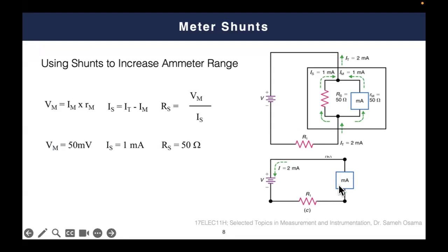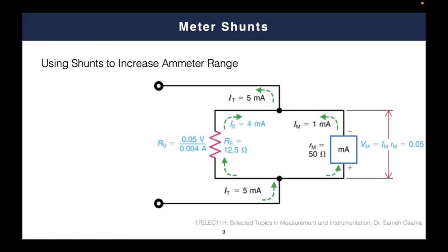So in this case, the current will be V over this resistance R plus 25 ohms. But if another colleague uses a different ammeter with a higher scale range, with this configuration, we have 50 ohm parallel with 12.5 ohm. So the equivalent will be relatively less than 12.5. Let's say it's 10 ohm.